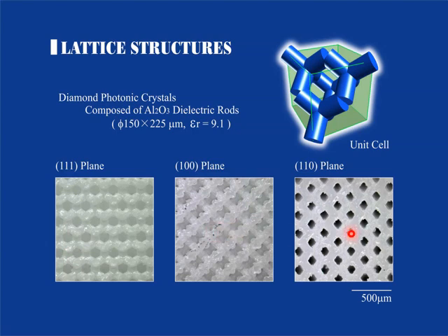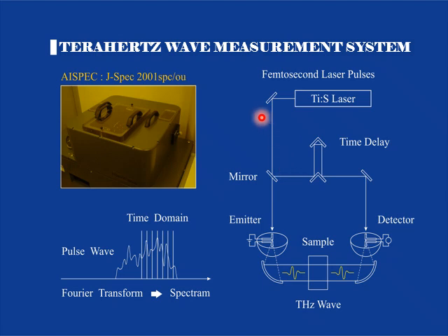You can see the micrometer-order alumina lattice and the translucent lattices. The relative density reached 99.8%, a high density. So we can create full ceramic diamond structures by using stereolithography and a heat treatment process.